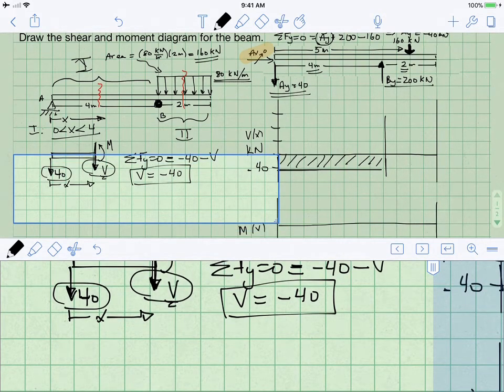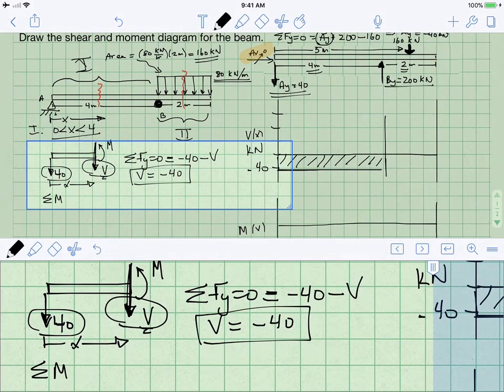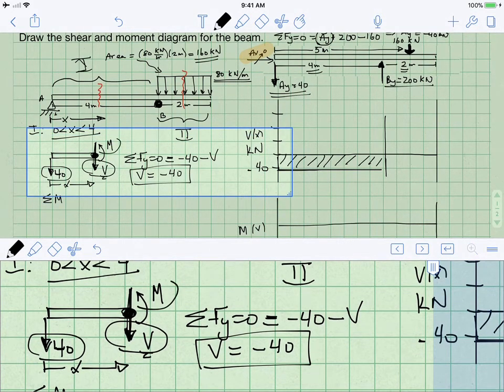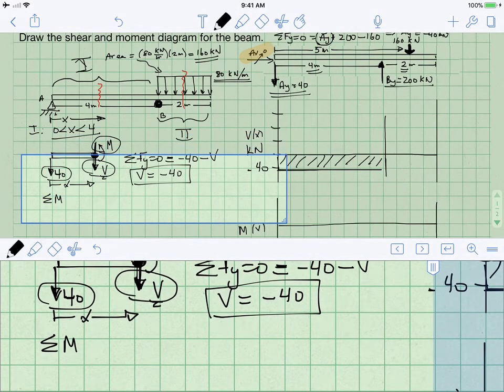So just like we did with the forces, we're now going to sum the moments, and we are thinking about what this position on the beam is feeling. First of all, it's feeling this bending moment, which is present in the beam. That's what we're actually solving for. So when we sum the moments at the cut, we must include that. So we write down this unknown M.